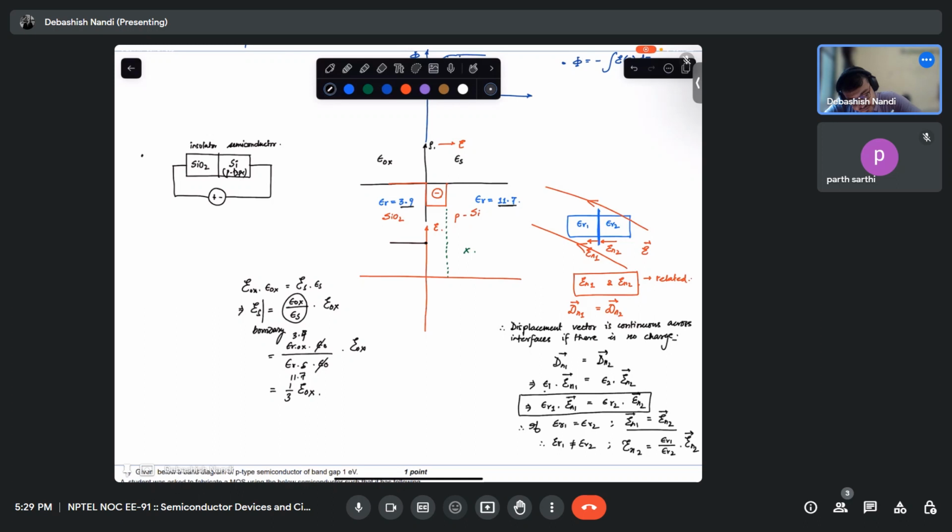That means at the silicon side you will have a jump here and then it will fall like a straight line, okay? Because it will get integrated, but there will be this distinct jump. And why is this jump or discontinuity in electric field happening? It is due to the fact that silicon dioxide and silicon do not have the same relative permittivity or dielectric constant, okay?